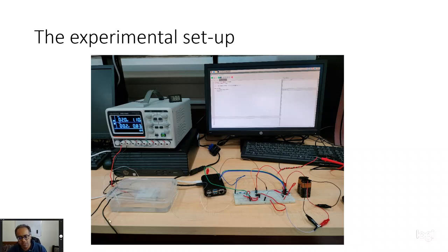This is the total setup, and once you write a very simple code on Thonny on the Raspberry Pi, it will continuously be reading out the temperature values. You can scale the temperature values or you can read it at the bit level. Now we'll go step by step and see how we can arrive at this final configuration from scratch.